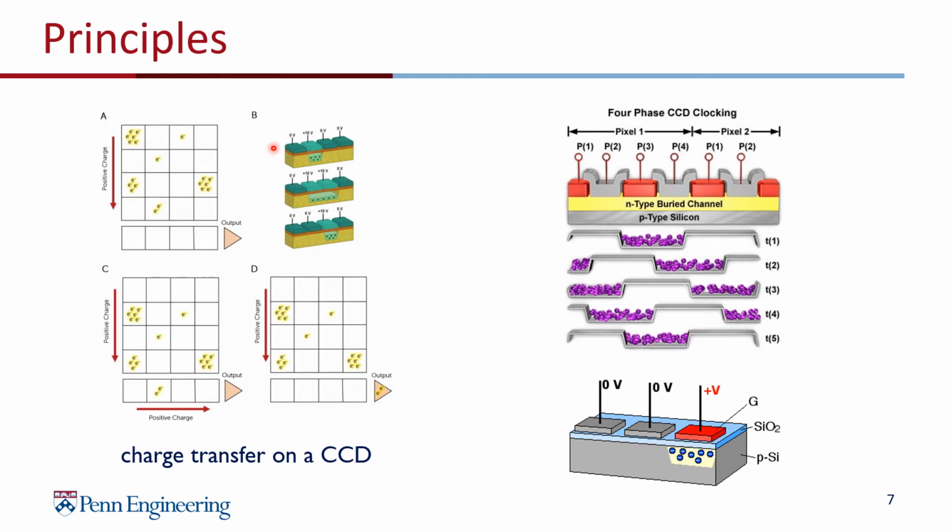There are no wires attached to each pixel. Instead, we make the electrons move array by array to the output. Each row of electrons is shifted downward using a positive voltage. The electrons are shifted by spreading the positive voltage over neighboring pixels to transfer them to a new pixel. This will continue all the way down the sensor until they are transferred to the readout register.